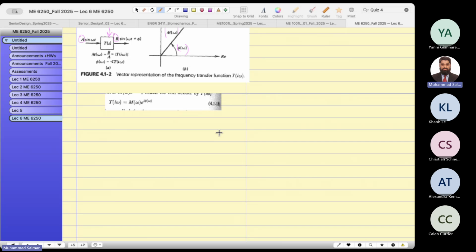So for example, if you have a mass here and spring here, and you have another spring here, rather than fixing this end, let's keep this end just hold this like you are holding by hand, and you are giving input. So when you move your hand slowly, then the mass will also displace slowly, and the displacement is very high at a lower frequency.